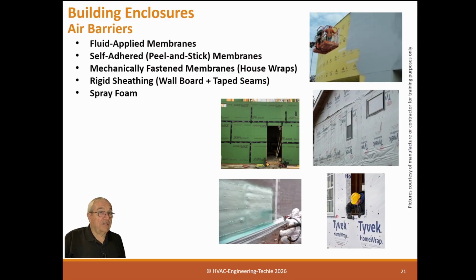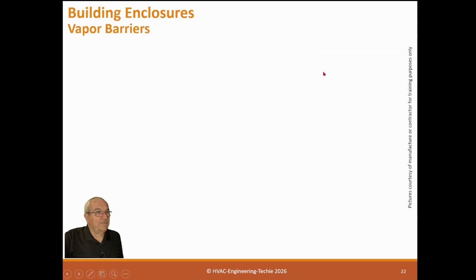So if it's sprayed-on insulation, your inspection has to be that it's on thick enough, because the installer is just spraying it, and he normally judges it like paint. Is it the right color? Okay, but it's a thickness problem. You have to inspect it, and you have to inspect all of it. You can't just inspect one piece and say it's right. It might be good here and not good over here, so you've got to look at it all.